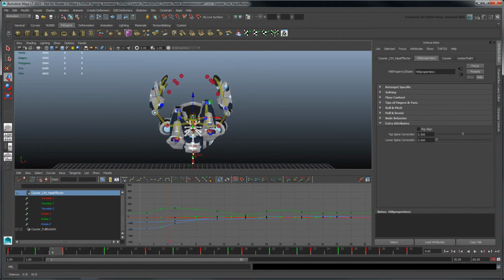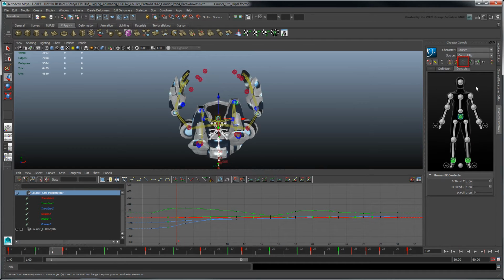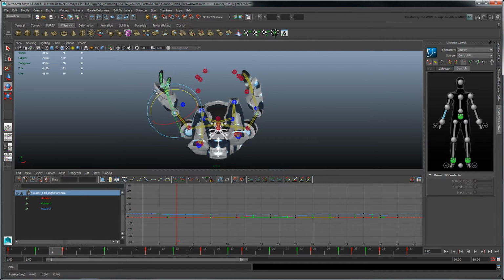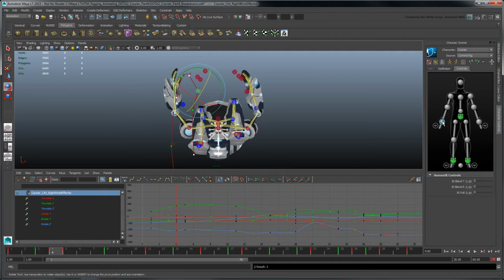Now that the control rig isn't aligned anymore, notice the offset between the IK and FK effectors in the Courier's arm limbs. To highlight this offset, go to Selection mode and manipulate the effectors. In this mode, human IK no longer evaluates the rest of the effectors. Show the skeleton on top of the effectors. The arm joints are currently being driven by the FK effectors. This is because the wrist effector's IK blend attributes are set to 0, or FK mode. Drag the sliders to blend the arm joint chain between the FK and IK solutions in both translation and rotation.